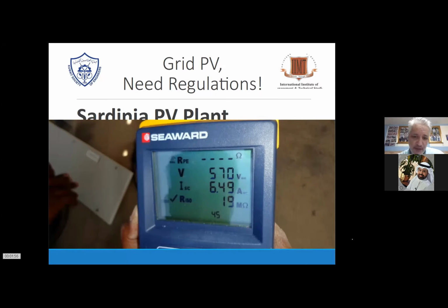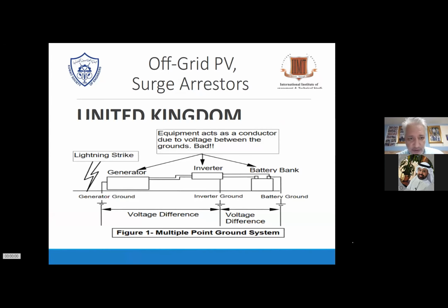Again, the inverter cannot see those values if there's no interconnection from the inverter earthing towards the tables, towards the modules, towards the roof. He will not see 19 megaohm. He will halve it down, so we are back at 600 kilo ohm or 800, and then he will not connect. It could be because of one string, could be one is missing, or some other issues.